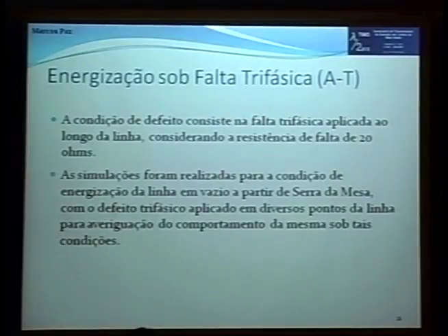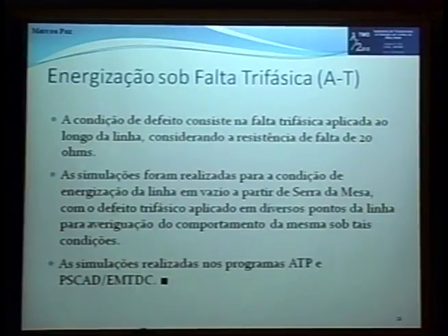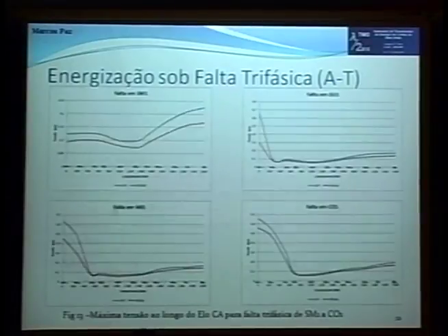Both for single-phase and three-phase faults, the line was always a no-load line. In the same way as the single-phase one, the three-phase fault was applied in several points so we could map the line to find the most critical regions. Simulations were also conducted with ATP and PSCAD.